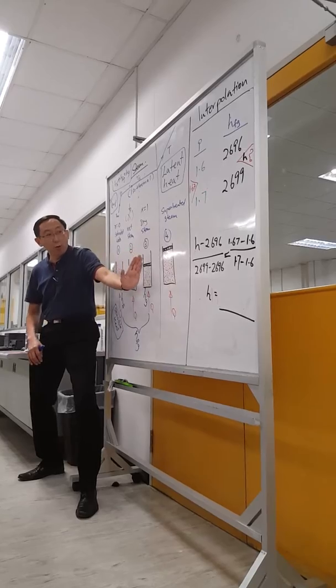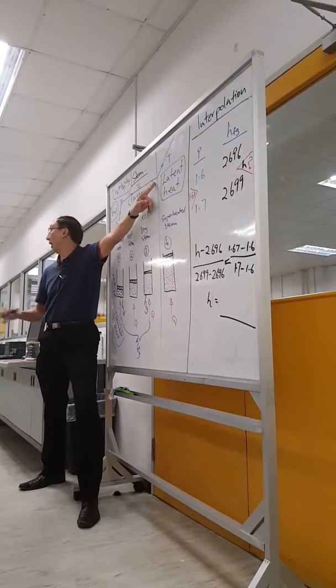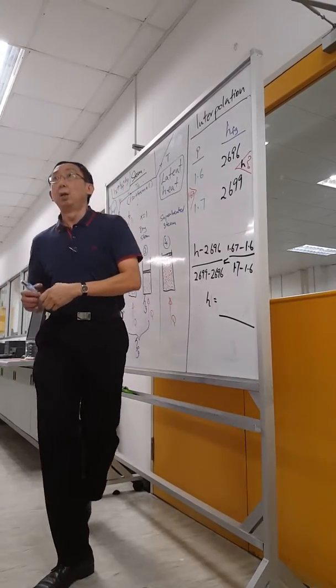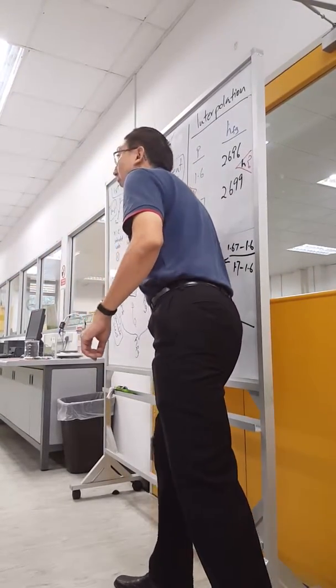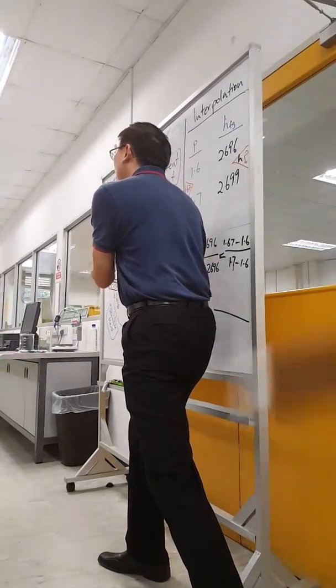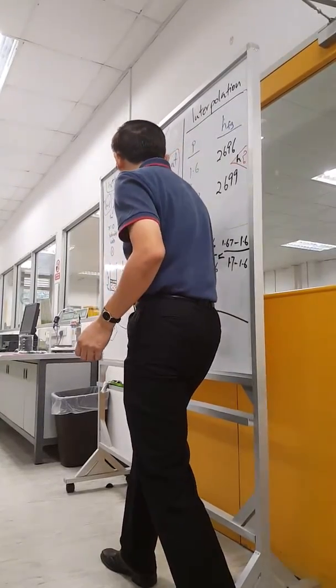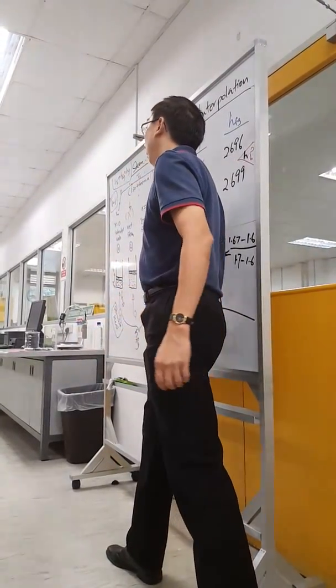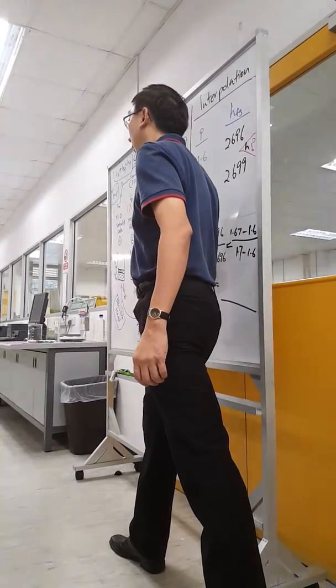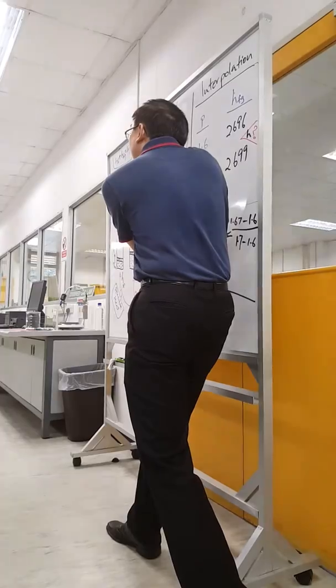Once it goes over this stage 3, it will no more behave isothermally. This is the maximum I can go. If you pump in some more heat, the temperature is going to rise. And when the temperature rises, it goes into the superheated region, stage 4. And you notice that in superheat, the steam actually further expands.